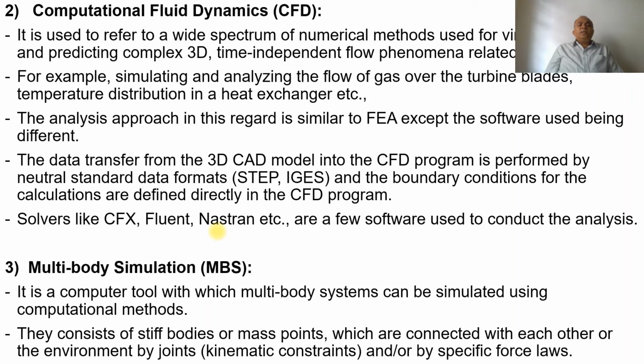The analysis approach is similar to FEA, except the software used is different. The data transfer from the 3D CAD model into the CFD program is performed by a standard data format, which is STEP or IGES, and the boundary conditions for the calculations are defined directly in the CFD model.